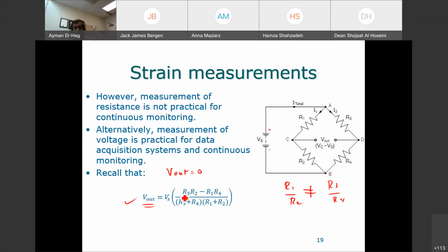So the question now is, why can the values of the resistance not be sent? That's a very good question. Because all the measurement systems that we have are based on voltages, not on resistance, and even currents. Even if I want to measure a current, I have to convert it to a voltage. So everything is based on voltage measurement. There is no device in the market at all that measures the resistance and then transmits the value as a resistance. Always it has to be a voltage.